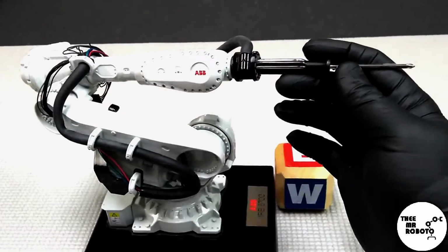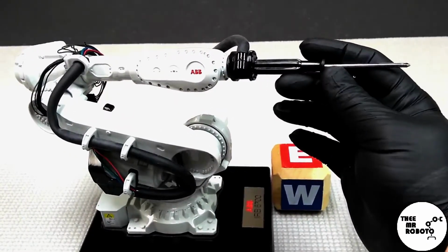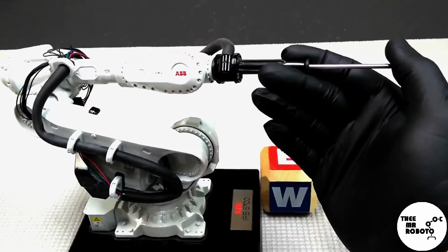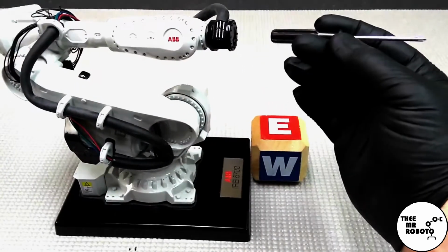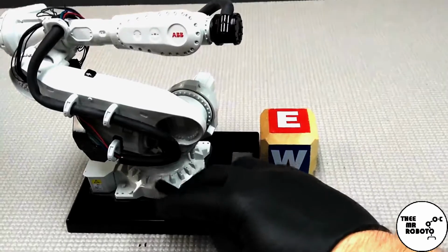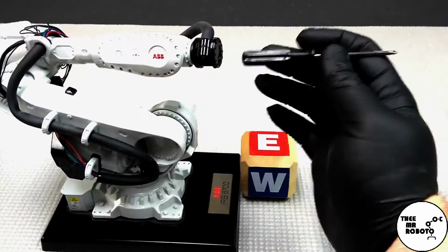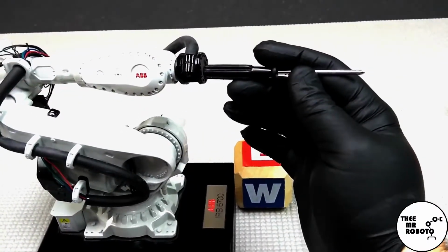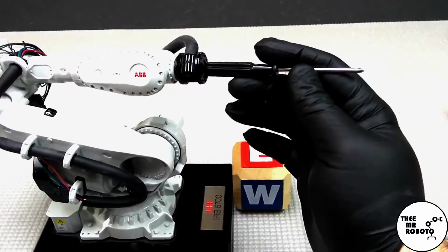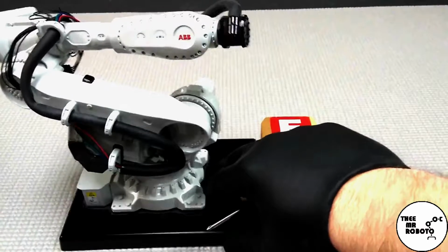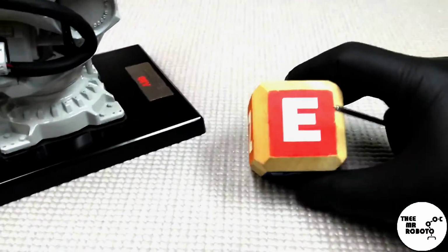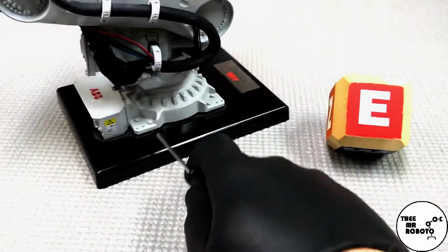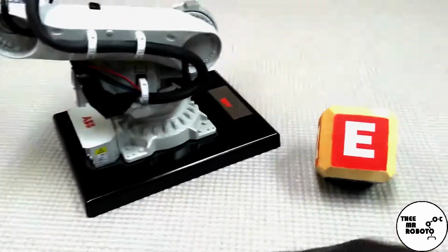So really the position of the tool center point here is, let's say, 1,000 millimeters further from your world coordinate system here, okay, than your flange. So tool center point is an offset of your flange coordinate system, and your work coordinate system or your base coordinate system here is a direct offset of world, okay?